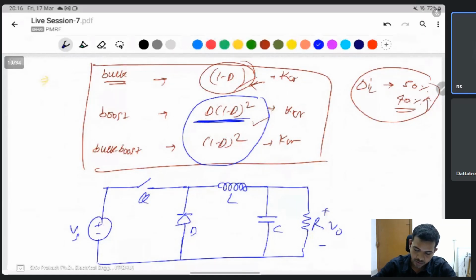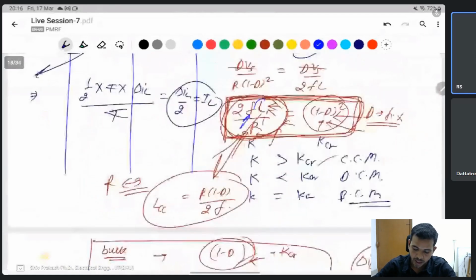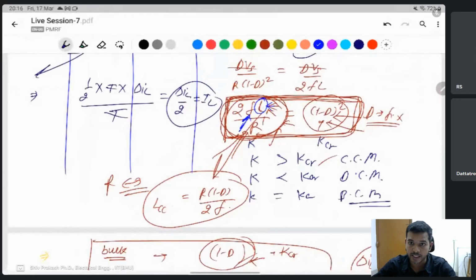then there are chances of being in CCM. Normally it goes into continuous conduction, because once you design a converter, you can't change the inductor value and the resistance value depending on the load. And D depends on the output voltage you want to find. You can't control D. D only controls the output voltage to regulate it at a fixed voltage. Then only you have the frequency to increase or decrease in light load condition.